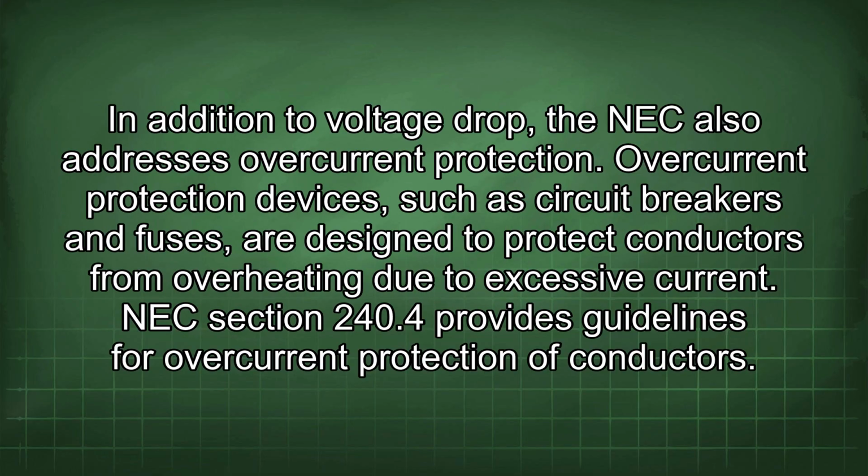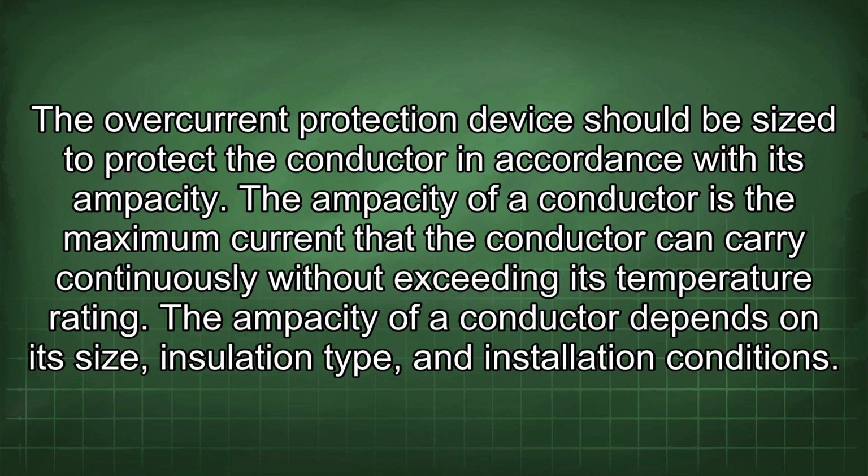In addition to voltage drop, the NEC also addresses overcurrent protection. Overcurrent protection devices, such as circuit breakers and fuses, are designed to protect conductors from overheating due to excessive current. NEC Section 240.4 provides guidelines for overcurrent protection of conductors. The overcurrent protection device should be sized to protect the conductor in accordance with its ampacity.